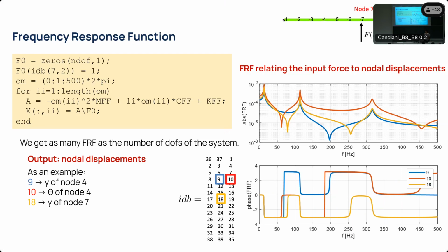So remember, those terms have a unit of measurement because they are meters over Newton. So if we give 1 Newton of force, we shall expect a movement of 1 meter. We give 10,000 Newton of force, we shall expect a movement of 10,000 meters. So remember, you always have to scale it by the magnitude of the force you give to our structure.